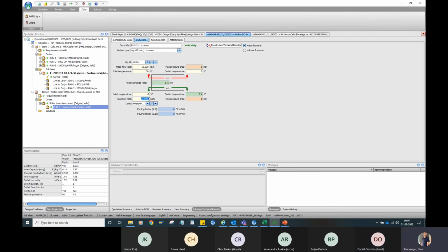So for example, if I try to lower this to 20, as it was on the countercurrent, you see I have crossed, the temperatures are meeting each other. And of course that is not acceptable or not possible. So therefore I need to increase the flow rate here. So I added 5,000 liters more, and now we have a delta T in this end of the cooling. Is that clear to all? Yes, I hope so. Yep. Save.